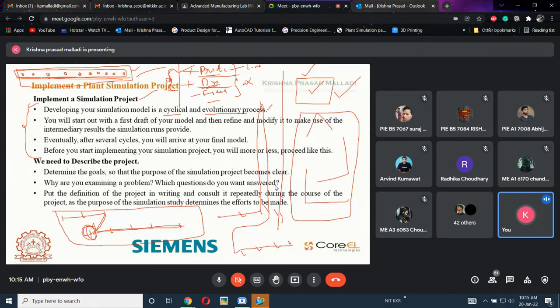Based upon the process, if after three machines the part needs to go for annealing, heating or quenching, then we can't place an oven in the middle of the plant. The part needs to go to the station where it is required. Once that is done, it comes back to its position and follows the line. This is called a process layout. Based upon the process defined, the product needs to move to that machine. Now, what is the fixed layout?